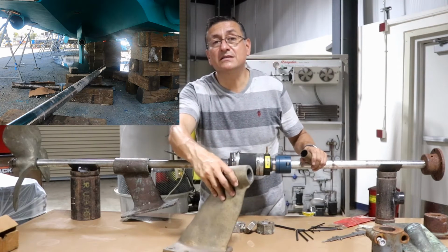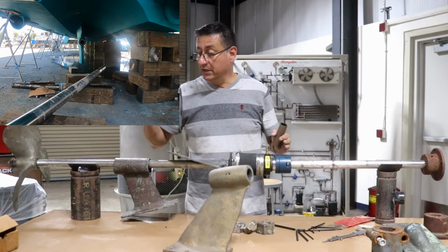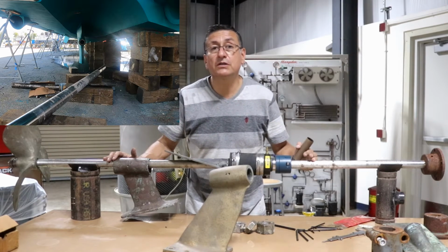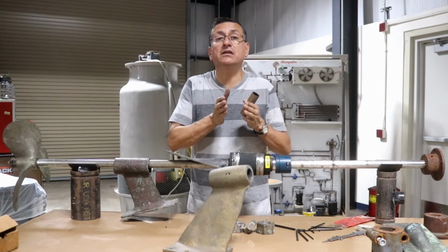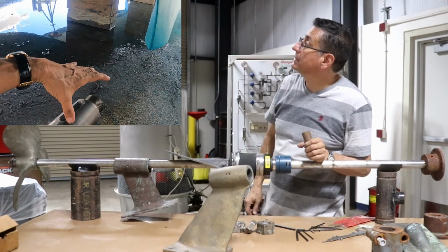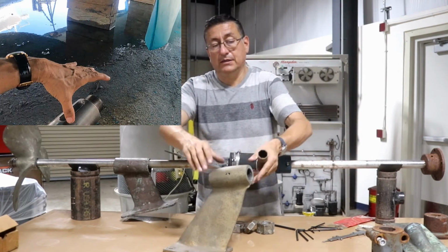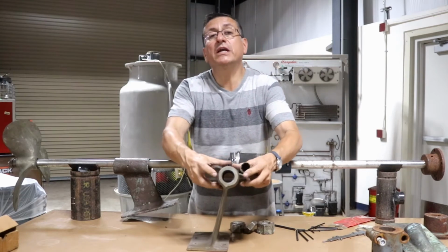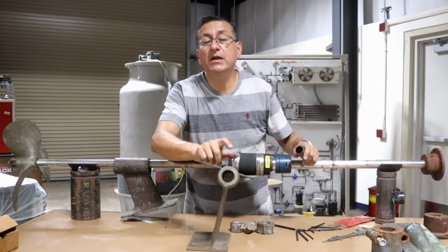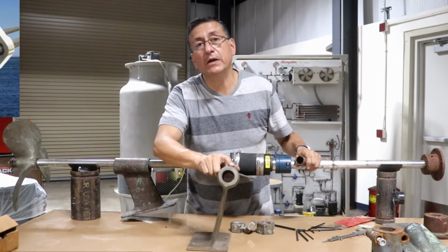And in some cases, like in the previous example, the shaft is a big shaft, more than 3 inches, a long shaft that is cut in sections and bolted one with the other, like this. The cutlass bearing can be replaced with mechanical tools similar to the tools used to remove the propellers.